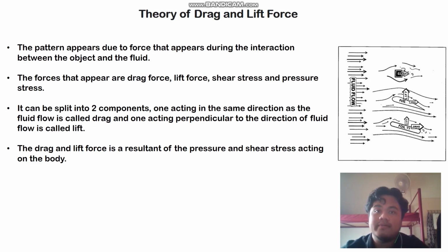Okay, next is the theory of drag and lift force. The pattern appears due to the force that appears during the interaction between the object and the fluid. The forces that appear are drag force, lift force, shear stress and pressure stress. It can be split into two components. One acting in the same direction as the fluid flow is called drag, as we can see here. One acting perpendicular to the direction of flow is called lift. So you can see here lift is perpendicular to the direction of fluid flow. The drag and lift force is a resultant of the pressure and shear stress acting on the body.